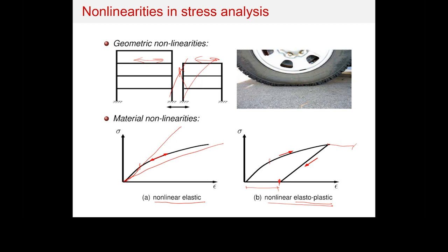This is quite obvious in polymers. For example, if you have a car tire, the car tire would deform quite significantly based on the pressure you have inside it. And then when you release that, it's going to go back to the normal shape. It's going to be zero strains in there. But even with polymers, even with this type of very elastic material, you will see that after several loads, or probably after a year or two, some cracks starting to show on the tire because of this cyclic loading.